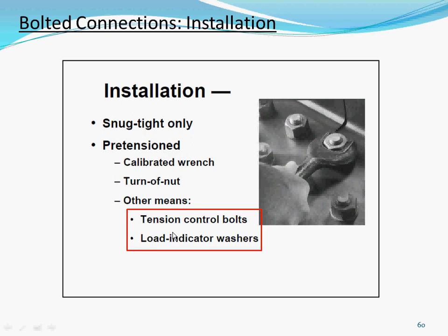So for our OMF, we're using the indicator washers, the DTIs. For the SMF, on the top we're using tension control bolts. So that's how we get the pretension in the bolt.